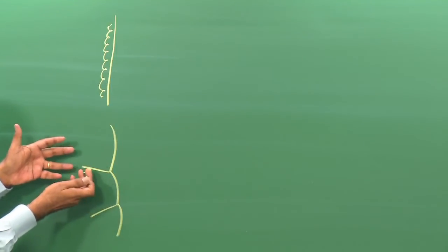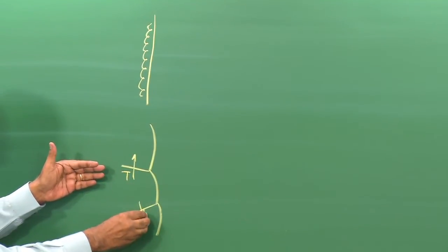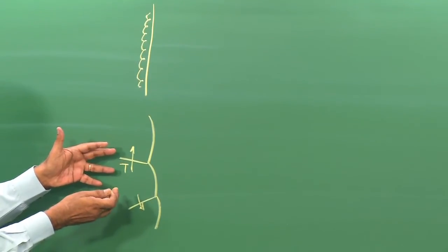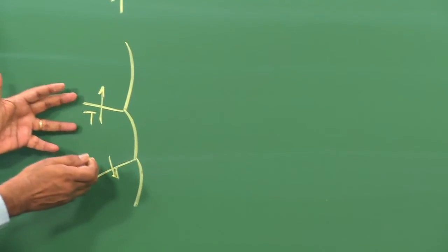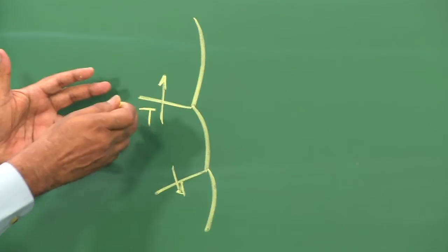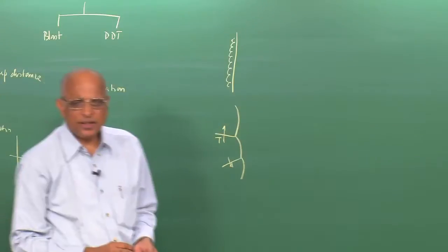A detonation seems to be multiple shocks in the front and lateral to it, and maybe these things move in this particular direction. Therefore, if we say a detonation is something like a multi-headed shock front or a multi-headed detonation wave, we should take a look at this before I start working out the velocities and pressure behind a detonation.